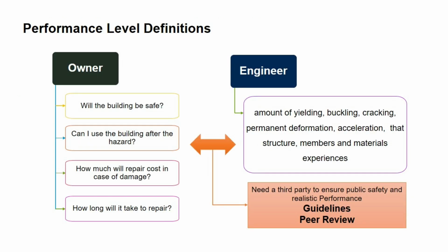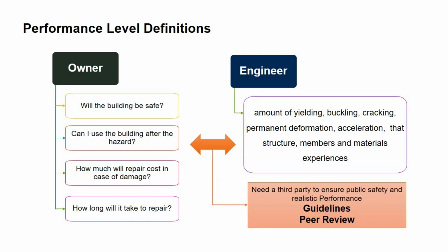So the summary is that in this approach, we answer all the questions asked by the owner in a manner which he can also understand. And how are we able to do it? Because of the nonlinear structural model, we know the amount of yielding or cracking or any other damage in any structural component for any level of seismic hazard. So we can answer these questions more meaningfully. For example, we can relate the repair cost with the amount of cracking or yielding in the structural elements. We can relate the time required for repair with all of these things. So whatever damage can be related to the amount of yielding or cracking in structural elements.